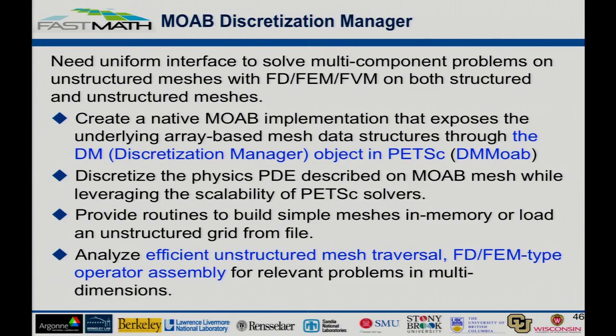So the MOAB Discretization Manager is a specific implementation of the DM interface. So we actually created a specific implementation for DM that sits on a native MOAB mesh so that you could use array-based data structures provided by MOAB. So you could basically load up the unstructured meshes with the partitioning information in several different formats and use that to discretize your partial differential equations.